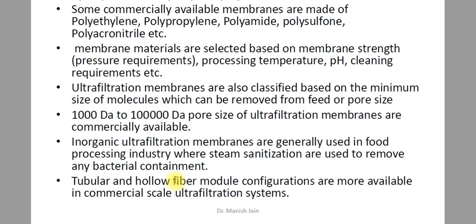But one more important thing is that in the ultrafiltration membrane, generally the feed flows in the shell side and the product flows in the tube side. So it is opposite. It is not that the feed flows in the tube side and the product flows in the shell side. In ultrafiltration membrane, the feed always flows in the shell side, so that the microparticles cannot start to clog the pores of the membrane, the tubes of the membrane. So always on the shell side you have the feed flow, and on the tube side you have the product flow.